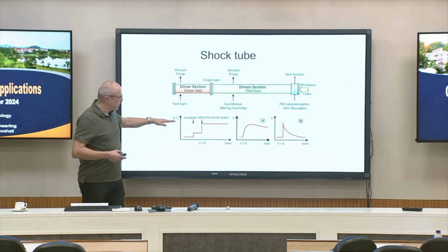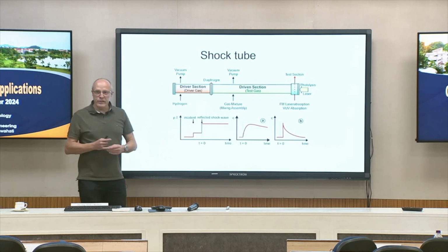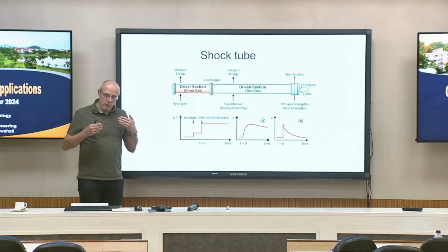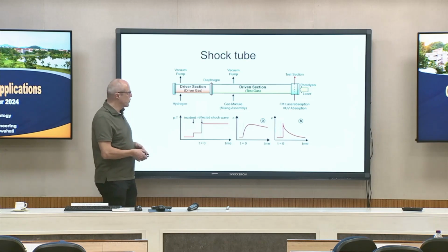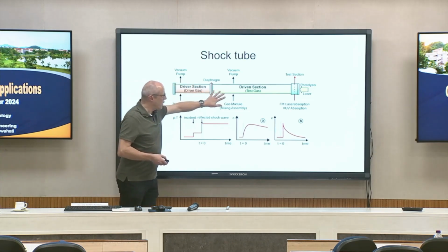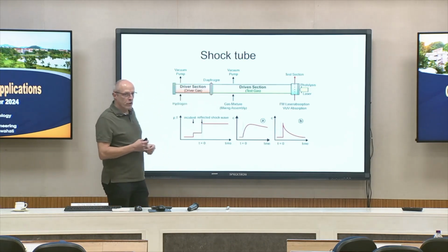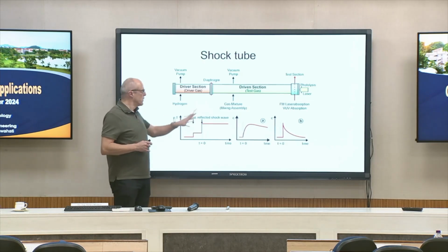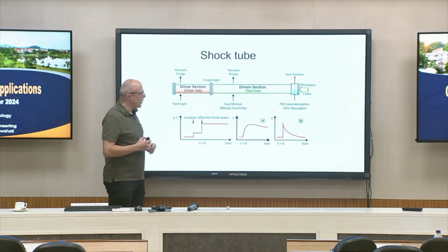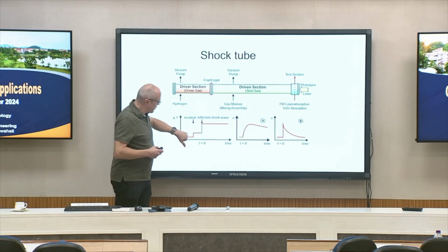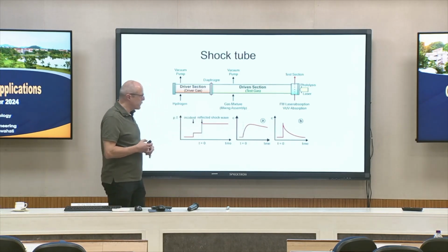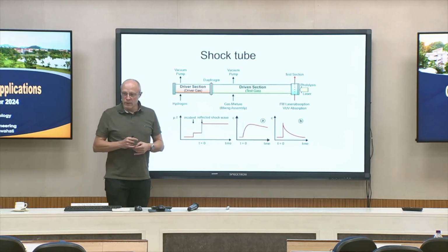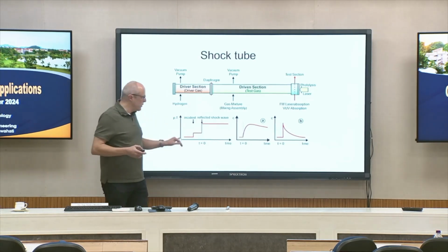This pressure and temperature, which we reach after the reflection of the shock wave, can be adjusted very precisely using proper pressure ratio, using proper driver gas, and so on. So we can really adjust precisely the interesting parameters here.